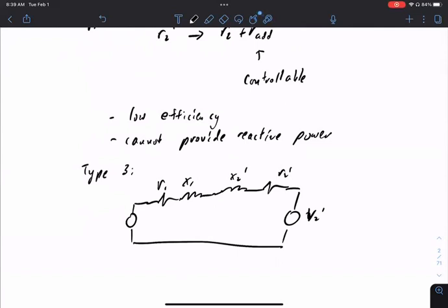Okay. And again, the benefit is this thing basically gets divided by S. Right? You have a slip. So any voltage you add here gets divided by S. So that has an amplification effect there. So even by adding a small voltage, you can get a big effect on the circuit.